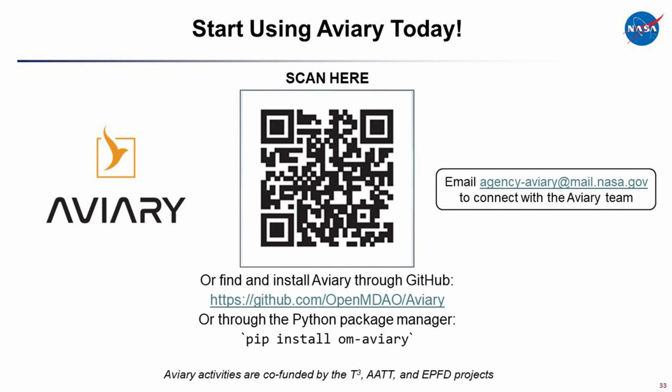Okay, here's another one. The level 3 interface to Aviary seems to still abstract the traditional OpenMDAO interface away. Is it straightforward to manually construct an OpenMDAO model using the groups and components in Aviary? Absolutely, yeah. So that screenshot of code that I showed is just one piece of this. That was a model we set up that was custom building. It was just a 737 model, but that was hundreds of lines of code. Some of them were using helper functions in Aviary, but sometimes we were directly interfacing with the OpenMDAO interface. That was, I guess I would say, a light use of level 3, where we weren't doing everything from scratch.